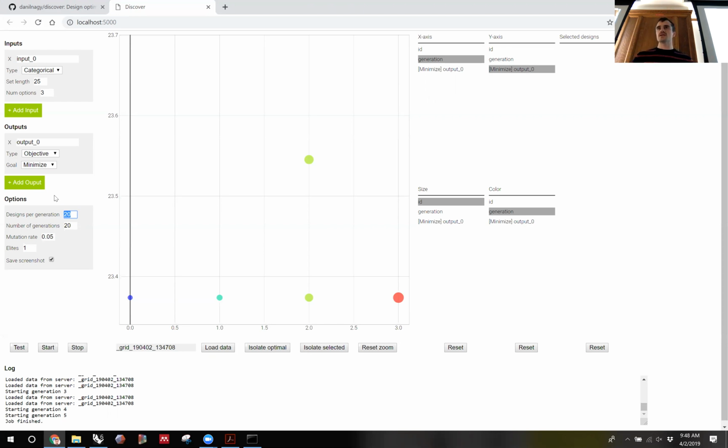You can just multiply those numbers together and you'll understand how many designs will need to be calculated by Grasshopper. So for the 100x100, that's 10,000 different designs, right? And how long that takes depends on how long your Grasshopper model takes to compute. So here, optimizing your model becomes very important as well. It's almost like when you're rendering a video, right? One frame might take only a minute, but if you think about 10 seconds of video, you have 30 frames per second, that's 300 frames, which takes 300 minutes, and you have to figure out how long that is. It's the same thing for optimization. We're going to be doing this over and over for these designs.